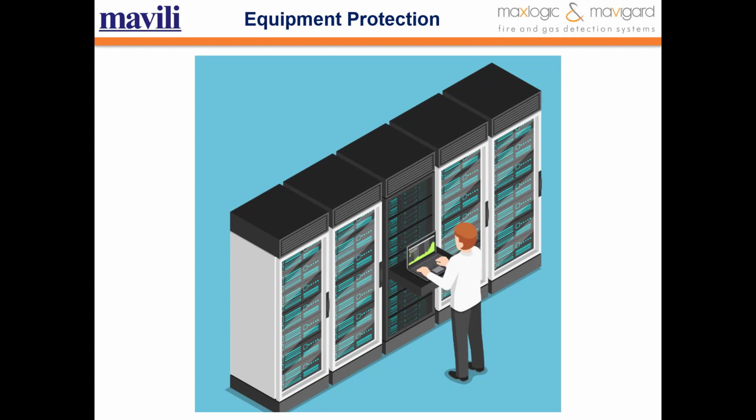Areas that do not require protection with automatic detection may include non-ventilated frozen food stores with gross volumes below 20 cubic meters, bathrooms, shower rooms, toilets, or water closets, provided that they are not used for the storage of flammable materials or garbage.